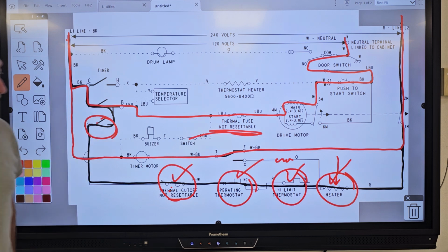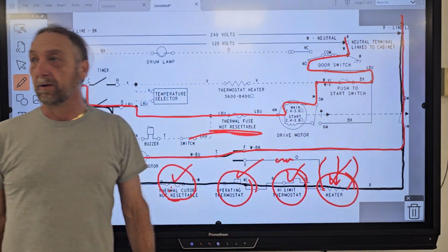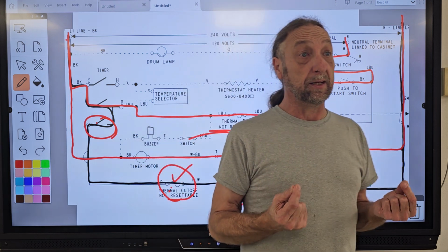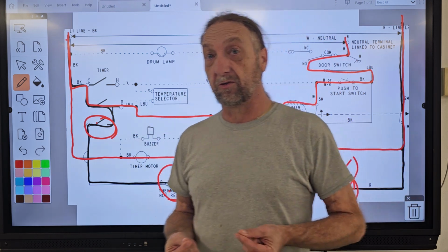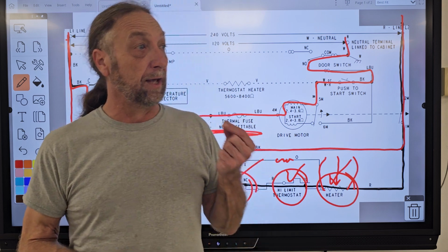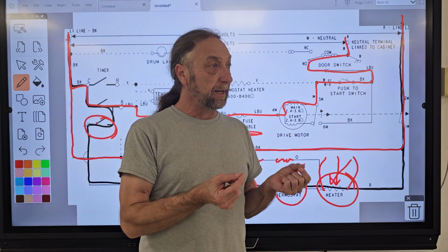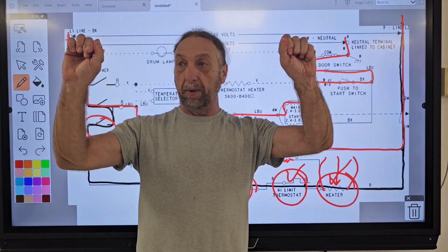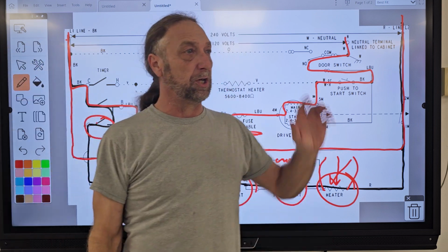So I'd save that as the last part I would check. But the very first test I would make is I would go right to the heating element with my meter, and we want to get alligator clips. So some of you guys competing, if you can get alligator clips, if you have meters, go on Amazon, and I want to make sure that you get two things. You want to get alligator clips that can slide over your meter leads, so you could clip the meter onto the two terminals of the heater, then plug the machine and press start.